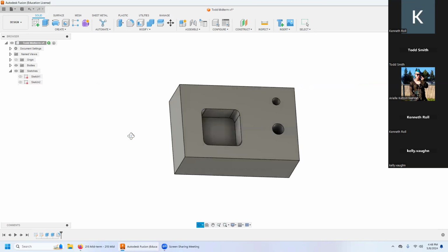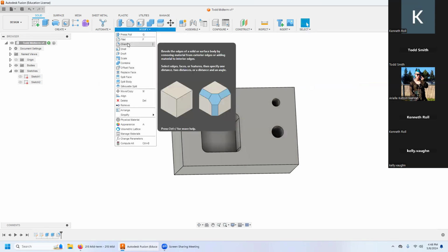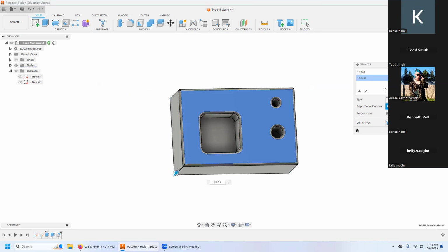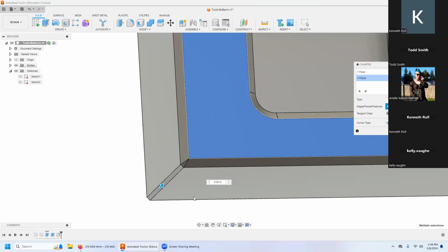Sketch off now. And now that we have that, let's go up here and chamfer. Everything wants a 50 thou chamfer. Okay. From there, I'm going to start a new selection set. I'm going to grab corner, corner, corner, and corner. Set that for 20 thou. Oh, it cheated. Look at that. Not supposed to do that.